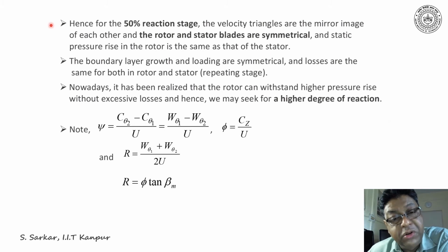Hence, for the 50% reaction stage, the velocity triangles are the mirror image of each other, and thus the rotor and the stator blades are symmetrical.